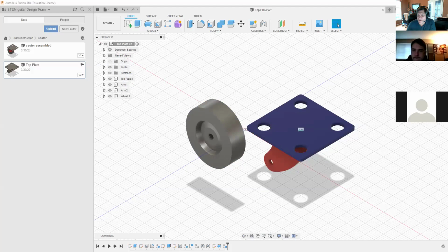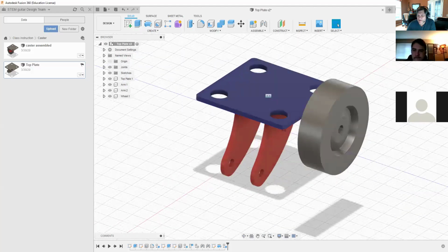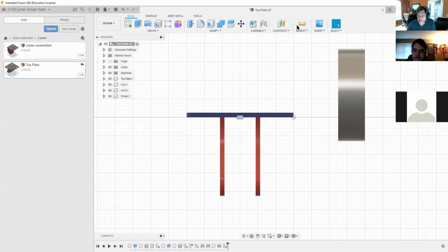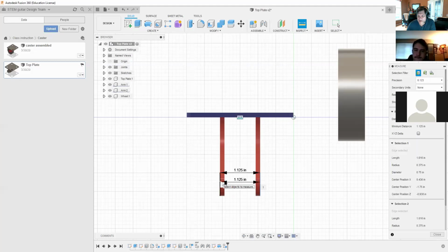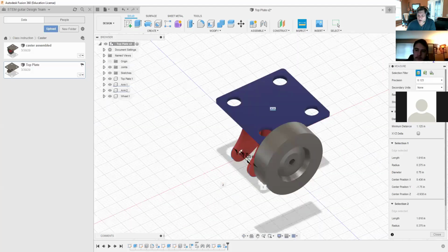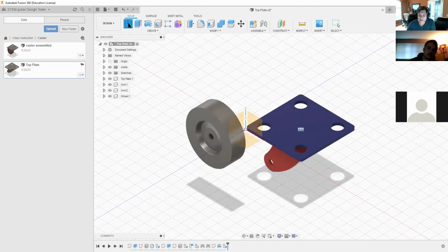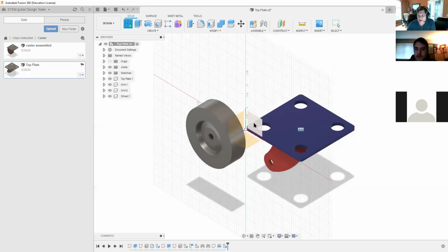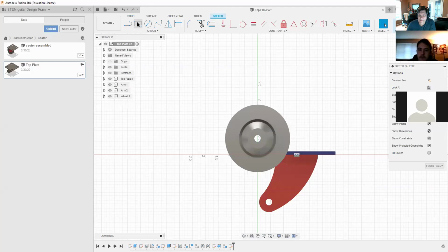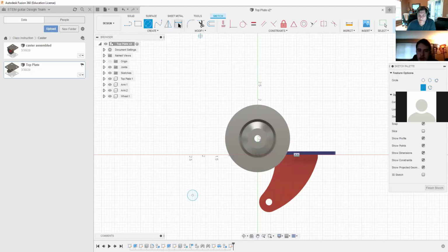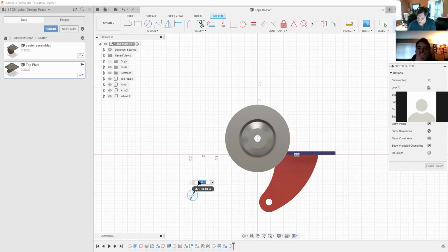All right. The final thing that we have to deal with is the shaft. And so we need to actually measure from the outside to the outside. And that tells us that it's 1.125 inches between the 2 openings. So now we need to create the 1/4 inch shaft at 1.125. So we can create a new sketch. Doesn't matter which way we want to go. We'll put it here. We'll draw the circle. We know that the diameter of the circle is 0.25.